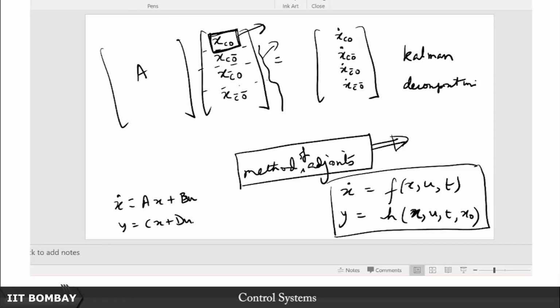So then you get into cooking up these cost functions, optimal control based formulations of what the control law should be, and even then it turns out that for these linear systems you often end up with a linear state feedback. So this linear state feedback isn't as useless as it might have initially appeared to be. Already of course you have seen that it allows you to place poles, but this linear state feedback can also be an optimal control law in many cases, when your cost functions have certain natures.